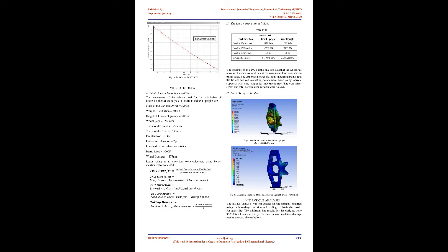4. Theory. Long before the LEFM approaches, e.g. Paris Law, 1961, to characterize fatigue failure were developed, the importance of cyclic loading in causing failures was recognized. The stress life approach is applicable for situations involving primarily elastic deformation. Under these conditions, the component is expected to have a long lifetime. If the stresses are low enough that the strains are elastic, the lifetime is likely to be long.